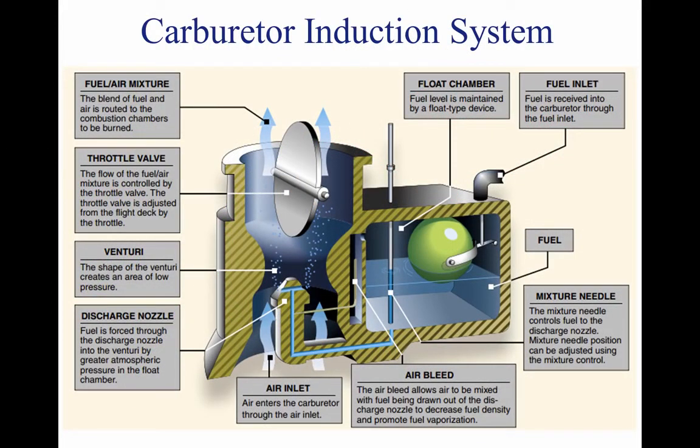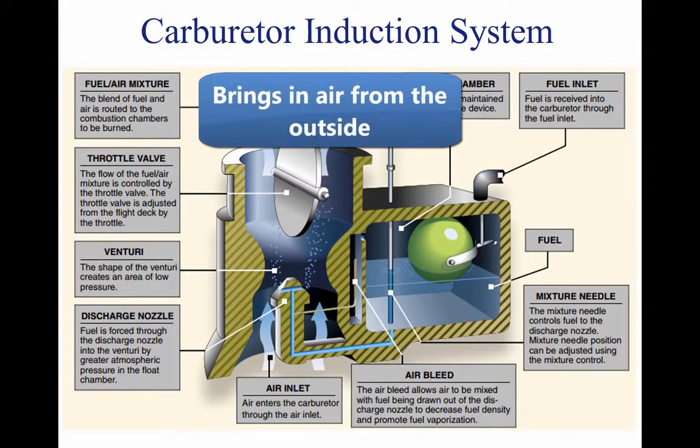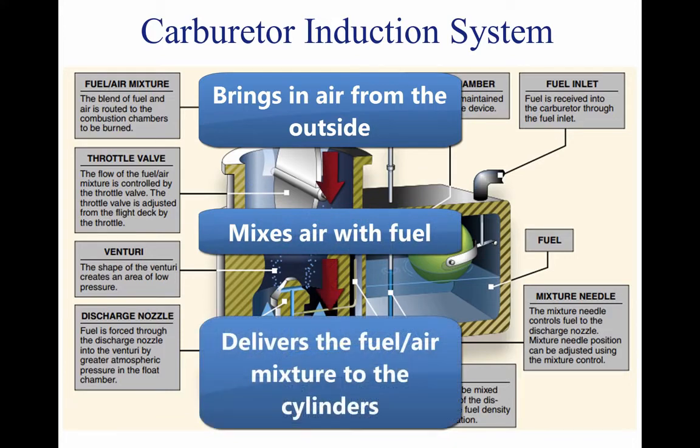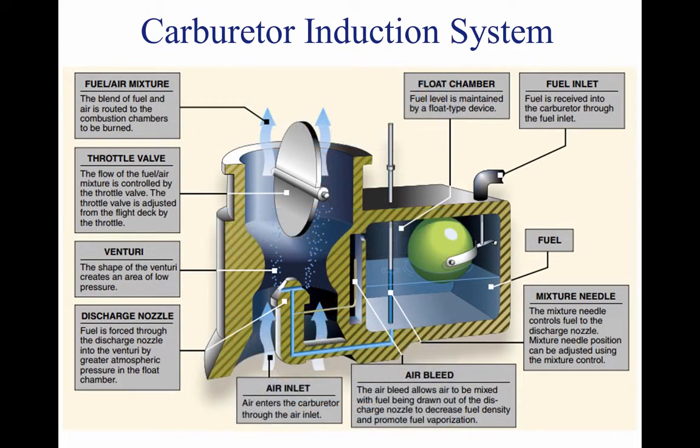Induction systems. The induction system brings in air from the outside, mixes it with fuel, and delivers the fuel-air mixture to the cylinder where combustion occurs. Outside air enters the induction system through an intake port on the front of the engine cowling. This port normally contains an air filter that inhibits the entry of dust and other foreign objects.